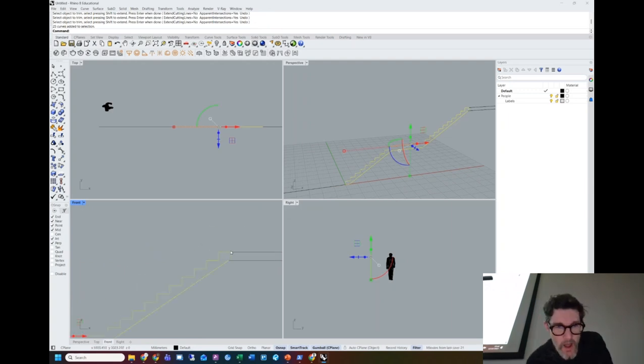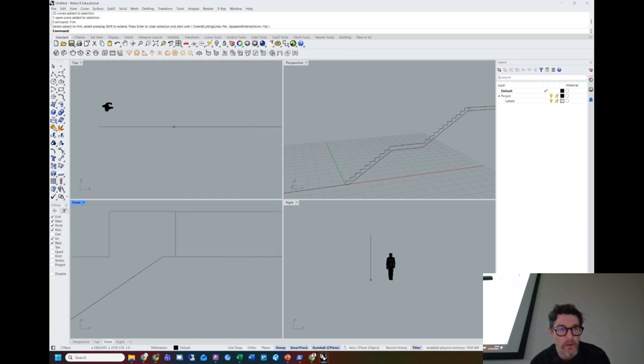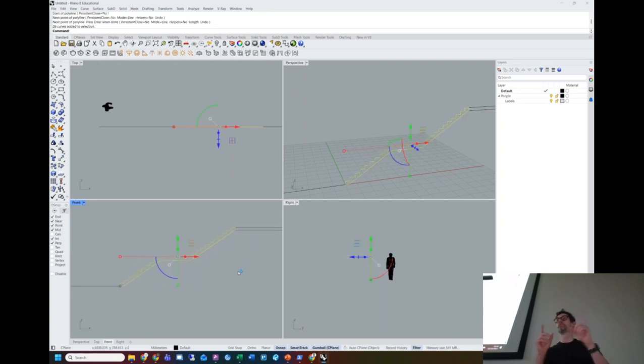And do you see there's one bit missing, which is this line here. So probably all I'm going to do is just bring that line out to there and then draw a line that goes from here to here. There we go. And now I can select all of those lines. Now they're not currently joined together. So what I'd like to do is I want to treat this like one block of extruded material, one piece of concrete that's going to get craned in and lifted into place. Probably in reality, this would be 2 bits, but let's just pretend it's one single precast element.